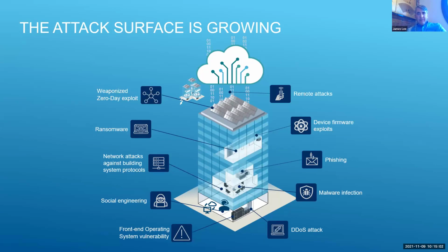In other words, if I make every variable air volume box a network drop on my main IP network, I'm opening up security holes for somebody to come in and attack my enterprise, my financial networks, anything using that network. We'll talk in a minute about what has been done over the last 20 years in terms of remedial security, and we're going to talk about where we're going.